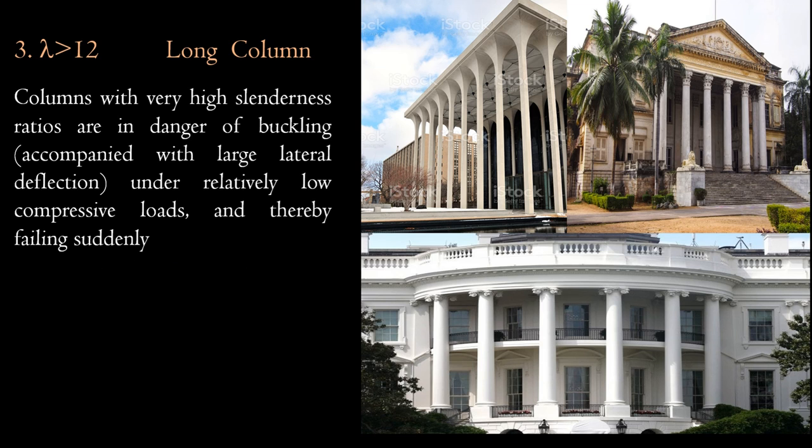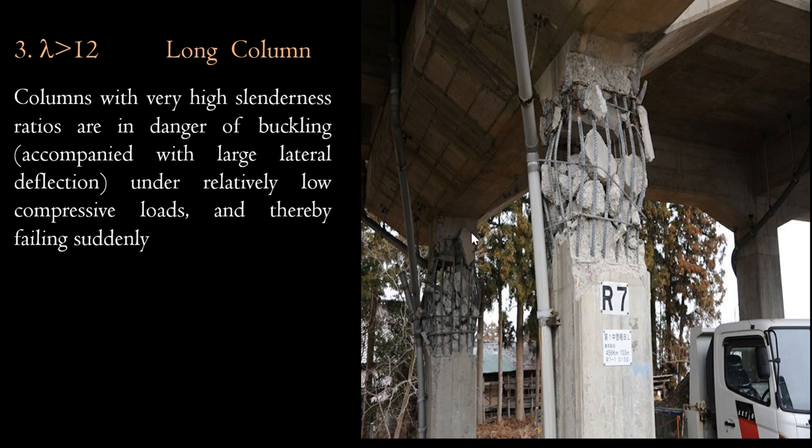So you can see here this happens. See, the last one happened by crushing. Here this column has buckled. You can see here there is some deflection. This is called buckling of reinforcement. This column failed by buckling actually. There are some other issues also, because you can see the concrete is not good here, but ultimately the column failed by buckling. Here for a long column, LEX by D or LEY by B must be greater than 12. That is, in any direction, if this slenderness ratio is greater than 12, then the column can be called a long column.